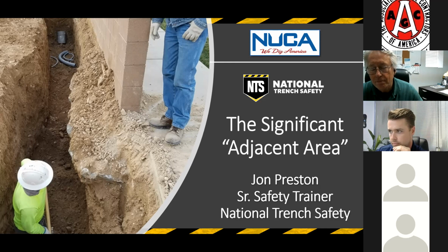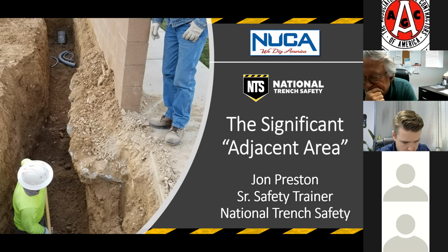Okay, the reason I asked about pinning the boxes, if you had to have 3 or all 4 pinned, is there's sometimes issues when we're putting in deep pipe and we have shallow utilities. So let's say we're using a 24-foot trench box in the bottom. Maybe there's 2 of them stacked up. When we come up to those utilities, we want to maybe remove the top 24-foot box, slide the bottom one under it, and then set maybe 2 12-foot boxes on the top so that the utility's in the middle. So that's why I'm wondering how many of those pockets need to be pinned.